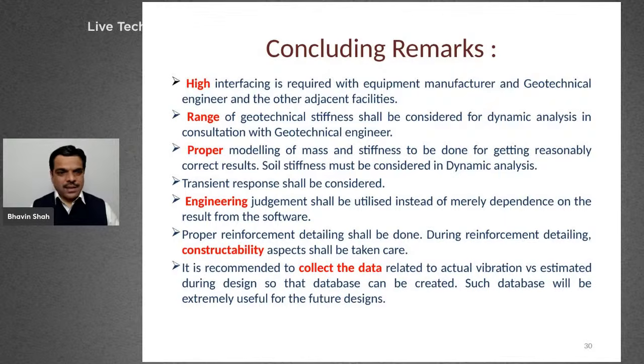So that's all. Quickly, I have tried to summarize a few points that you shared through the registration form. As a concluding remark, high interfacing is required with the equipment manufacturer, the geotechnical engineer, and the other adjacent facilities. Wherever we put this vibrating equipment foundation, interface is required with the surrounding foundations also.